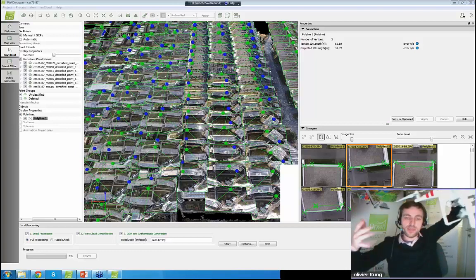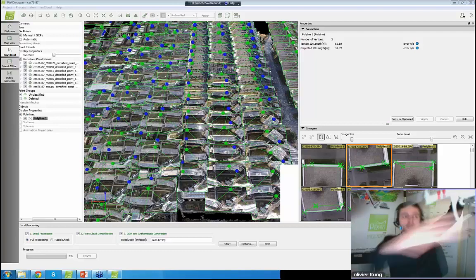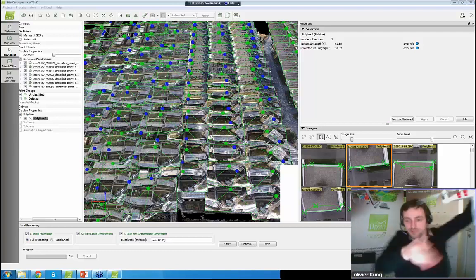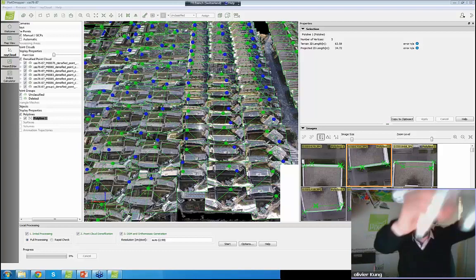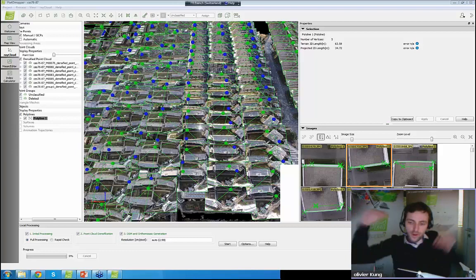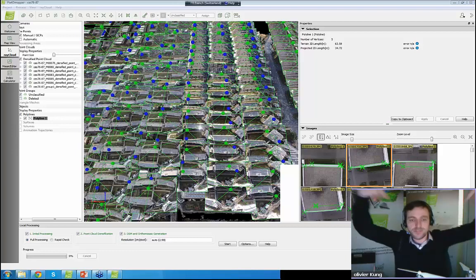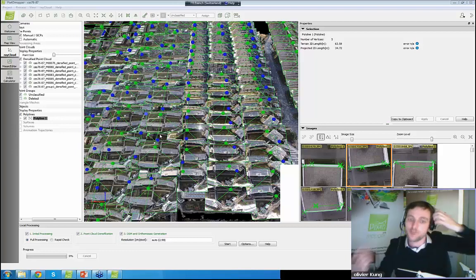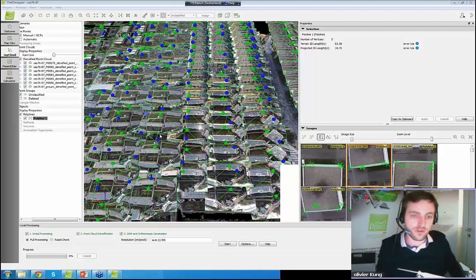And then if you do another grid, which is rotated by 90 degrees versus the first one, and you do this grid again, then you'll have all 4 sides of your buildings taken with a 60-degree angle. And there, of course, the accuracy and the resolution on the facade is going to be much more improved.